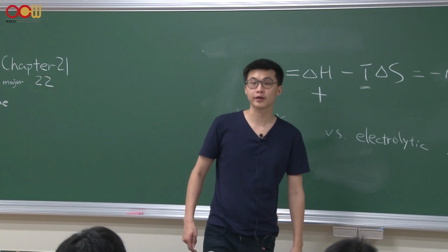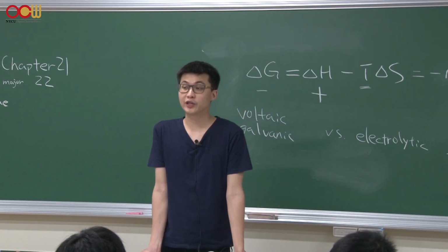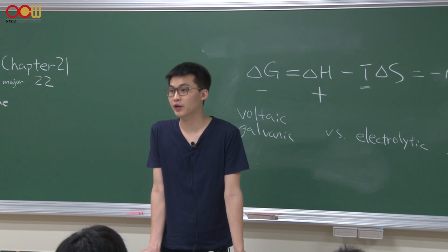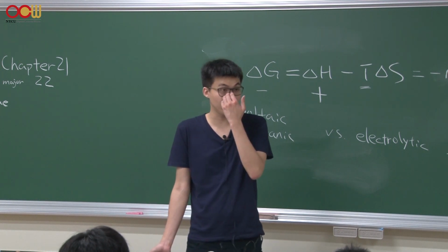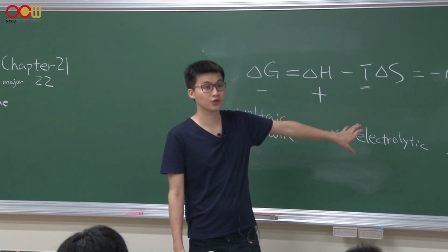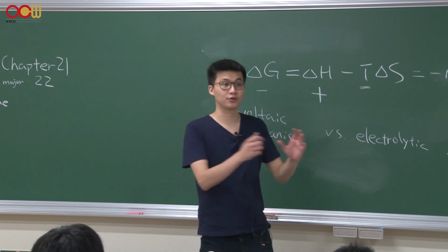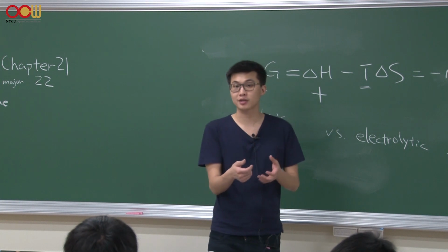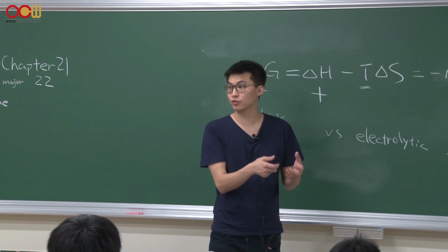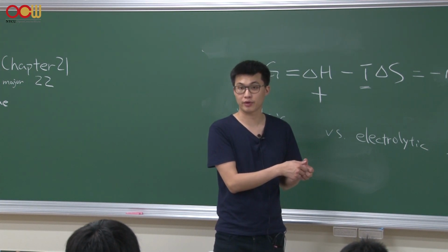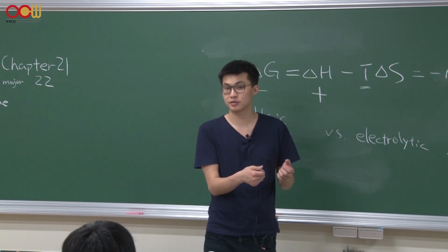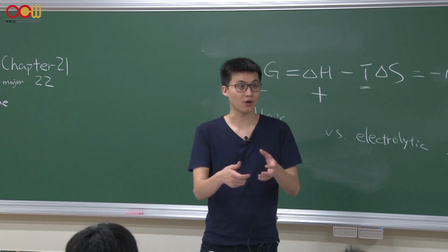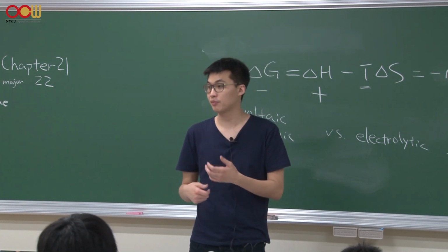Okay, so theoretically, in your recharging process, you're putting an external power supply, you're putting external energy back into your battery. You really hope you can push the equilibrium back to what the fully charged battery was. However, that process never happens. It's really difficult to go back to the original state completely. There can be many reasons. So the amount of reagent you can work with decreases over time. That's why the lifetime decays.